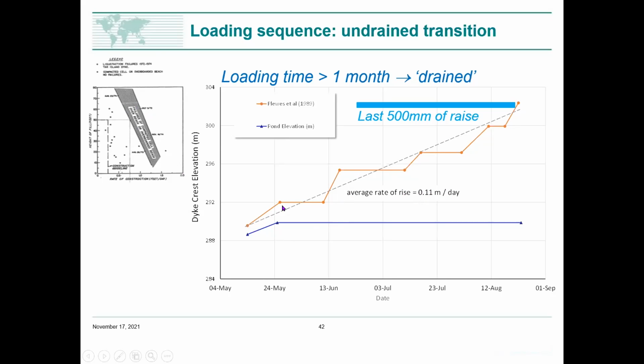And we said, okay, if we take a characteristic drainage distance and a characteristic hydraulic conductivity, which we'll pull off from Hazen's formula, and if we look at a compressibility, which was not going to be a million miles removed from lambda 10, we can calculate a CV, and we can work out a time factor.